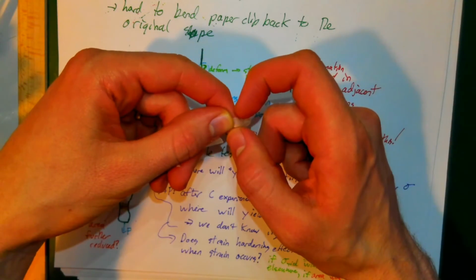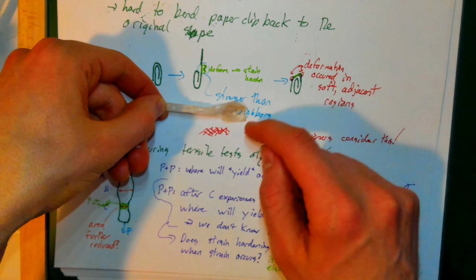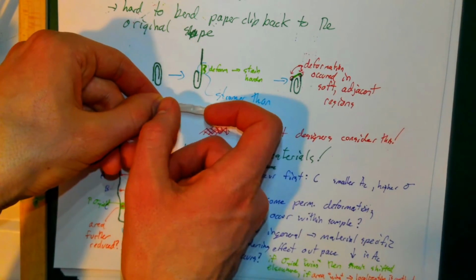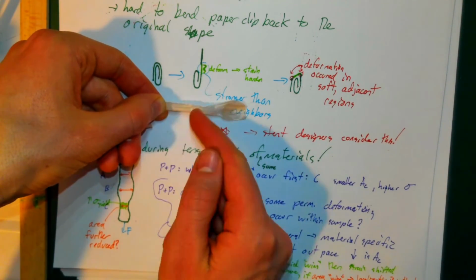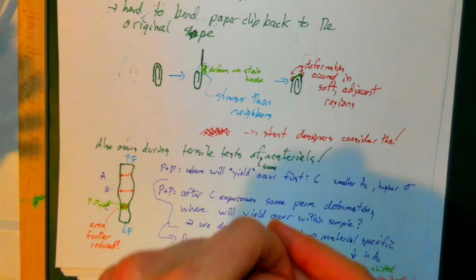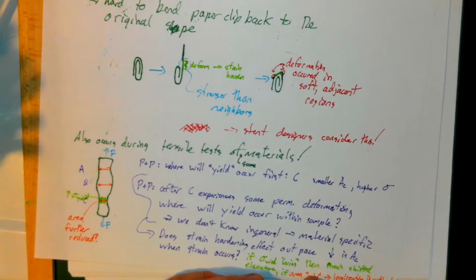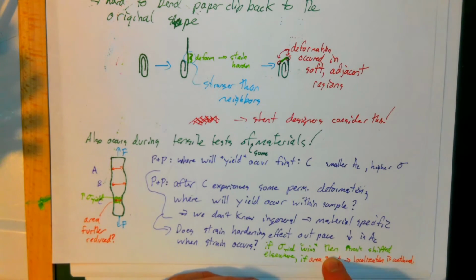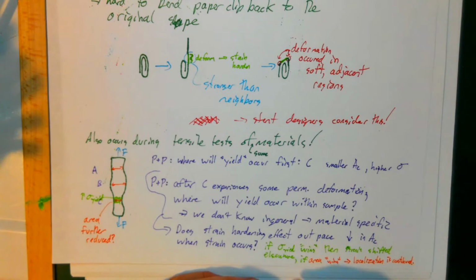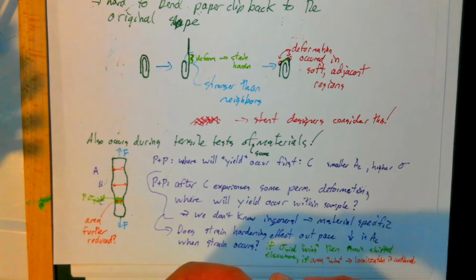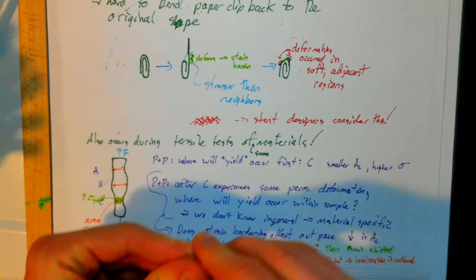It started getting smaller. And all of the strain, right, basically this stayed just about as thick as it did originally, and the strain kind of continued happening in this region. So the plastic bag is an example where the reduction in area outweighed the increase in the yield stress, and this necking phenomenon occurs.